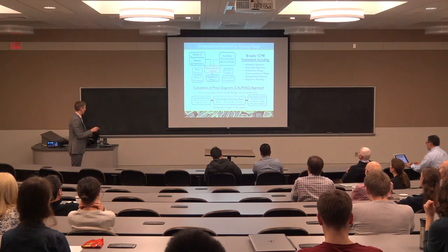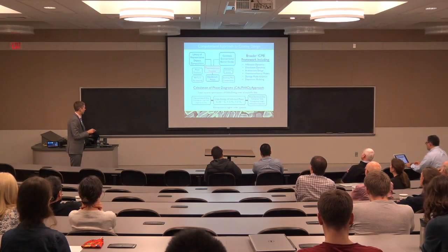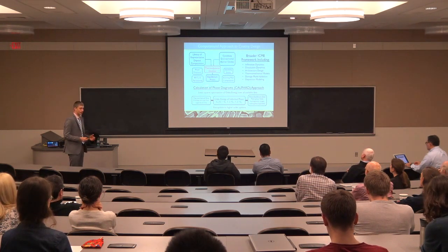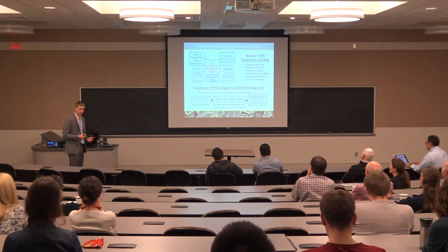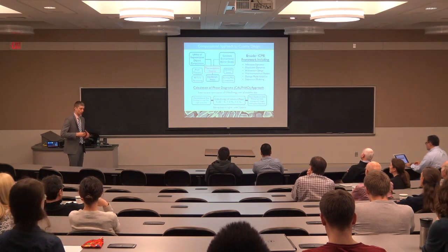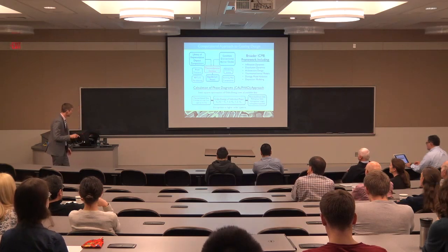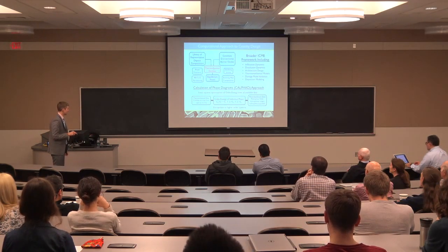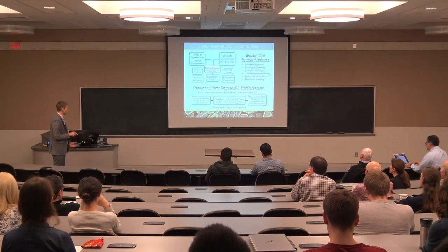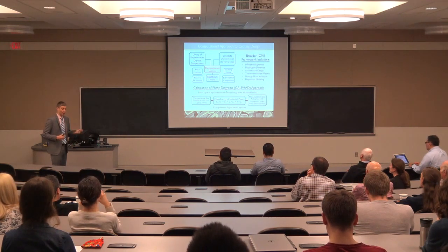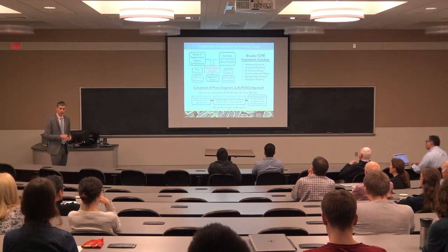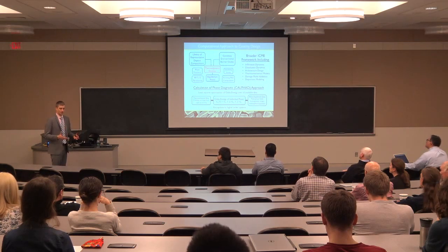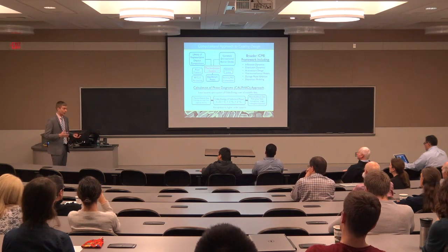And the way that these thermodynamic databases work is this approach called CALPHAD, or the calculation of phase diagrams, where ultimately what we'd like to have is a Gibbs energy description of every phase in the system, be this a ternary system or a 7 or 8 component system. And we develop that understanding of the Gibbs energy of each phase using a combination of thermochemical data, measuring heat capacities, enthalpies, etc., as well as an understanding of the phase equilibria. Because ultimately, the phase equilibria phase diagram is just a representation of the interplay between the Gibbs energy of the various phases in the system.